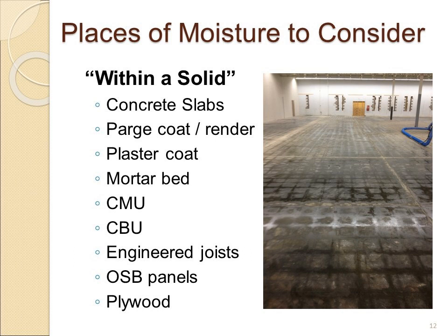All of these, having cement, are going to absorb moisture from their surroundings. Some of the moisture is going to be in the installation, in the mixing process, adding water. And the other condition is that once in place, weather, humidity, all these things could add moisture or delay these products from fully curing out for an extended period of time.